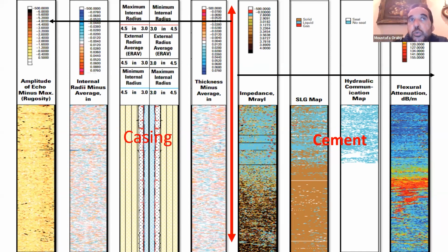Okay, so in this case, you will know if you have corrosion inside the casing. It will also give you the diameter of the casing outside, so the internal diameter and external diameter. The internal diameter is controlled by the frequency of the arrival. So the internal diameter will be measured, the external diameter will be measured. If you have corrosion on the external, it will let you know that. If you have corrosion inside the casing, it will let you know that. If you have scaling inside the casing, probably you can also find this out.